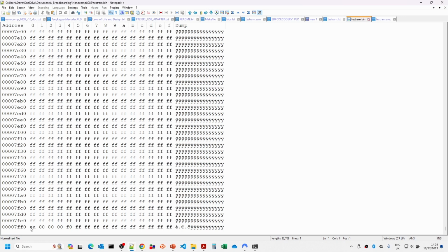So what this indicates is that the place where it should be jumping to will be F000 in the code segment and 8000 in the instruction pointer. So if we go to the top, you can then see that we've got B8 0000 BB 0000. So that looks like that's the code that we were expecting. Okay, so we just need to now burn this into ROM.